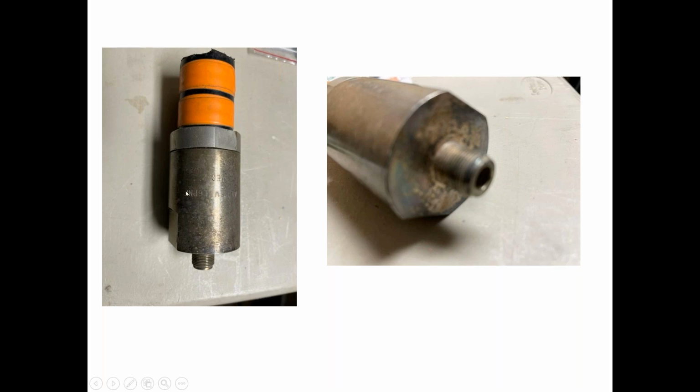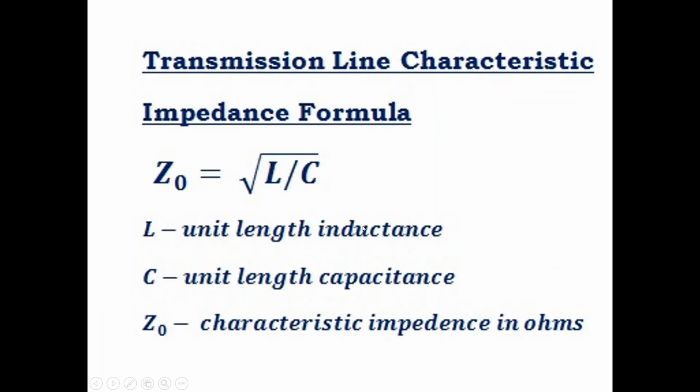Here we have a connector going between, I think this is a 7/8 cable, into a 50 ohm cable. There's no loss here. There's minimal loss, we'll talk about what's called insertion loss, but there's almost no loss here because 50 ohm to 50 ohm, it doesn't matter. So you can connect the thinnest cable to the thickest cable depending upon what your needs are, and you'll have a seamless flow of the RF signal through that cable.